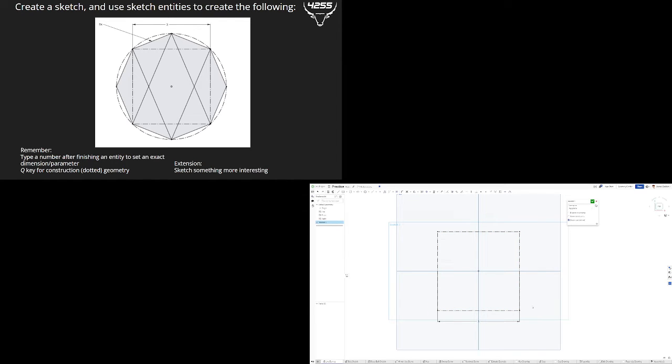And then I see a polygon here, an 8-sided polygon, and because the diameter is being defined on the outside of the polygon, I know that this is a circumscribed polygon. So I'm going to go ahead and create a circumscribed polygon. Again, the center point is the origin. That's very important. I keep using the origin here as my center point.